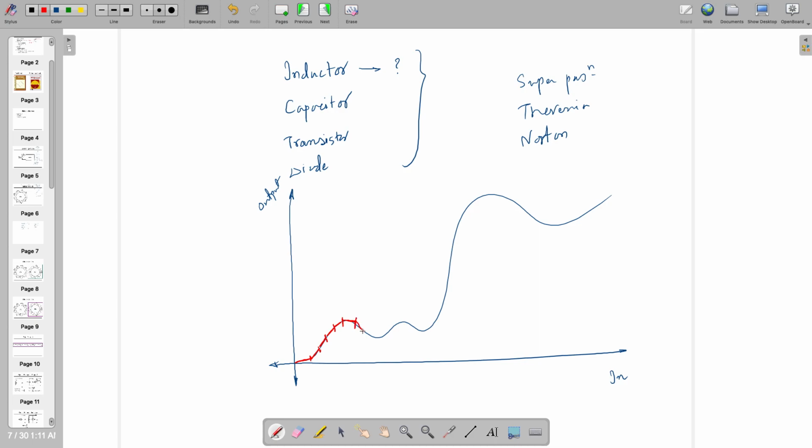I'm breaking it into small pieces, and I'm going to analyze from 0 to, let's say, some v1, then till some v2, then till some v3, because from 0 to v1, for a small value, it's linear. This kind of approximation is known as piecewise linear, right? So this is what we are doing, and we are following this principle that it's non-linear, but I'm going to only take care of a small part, and that is how we land up in small signal models.